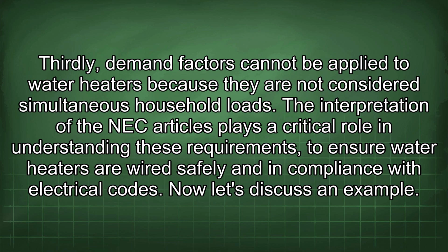Thirdly, demand factors cannot be applied to water heaters because they are not considered simultaneous household loads. The interpretation of the NEC articles plays a critical role in understanding these requirements to ensure water heaters are wired safely and in compliance with electrical codes. Now let's discuss an example.